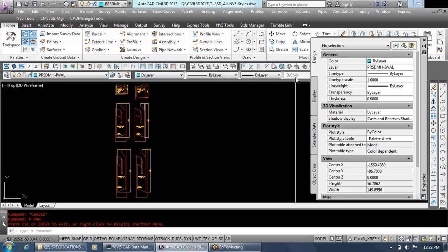That being said, I know that in some cases you'll just want something quick and dirty, and a simple box may serve you well in your pipe network. So I have developed pipe network parts and styles for D1, D2, and D3. Just know that you're not going to be representing an accurate 3D model of those parts. They're going to be pretty generic. But if you're after something generic, it's there for you to use.